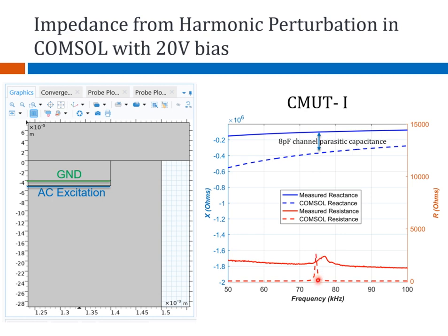Why is that? Because the pressure acoustics are not enabled, first of all, in the backing, and the dampings are not available. So I'm going to show you how, if you include the damping into the glass substrate, then you're going to have those baselines. If you include the damping, then of course the Q is going to get lower, and the simulated resistance baseline is going to match what is being measured, which is suggestive of the damping or the vibrational loss in the backing.